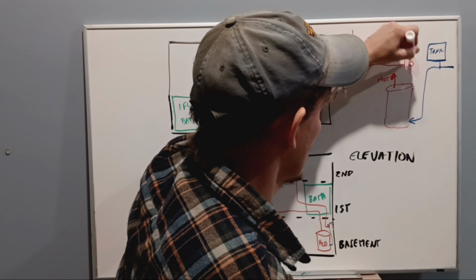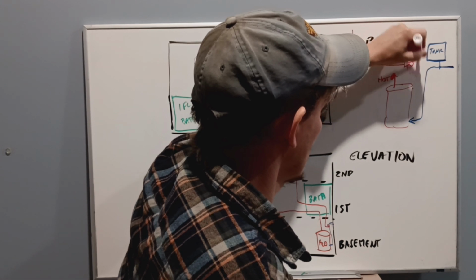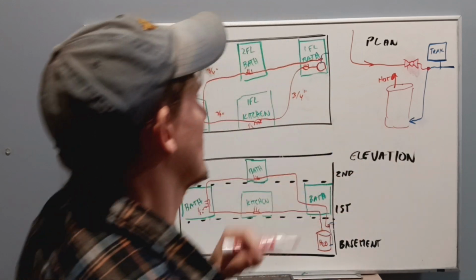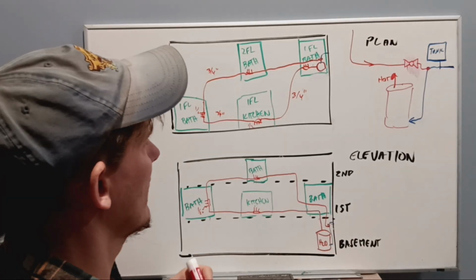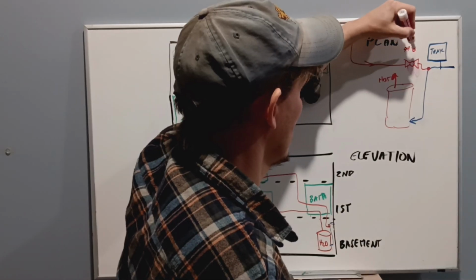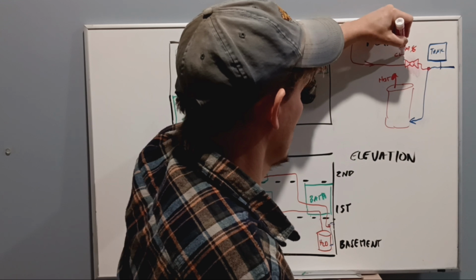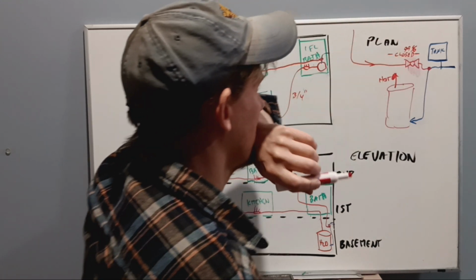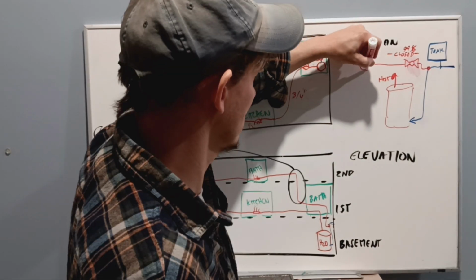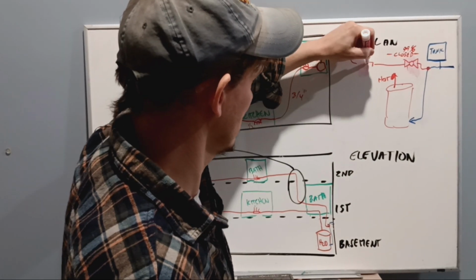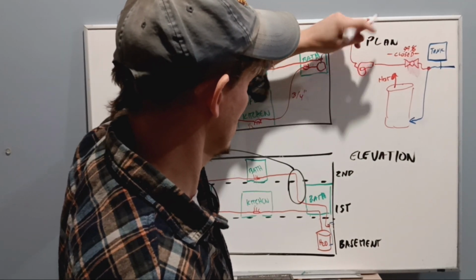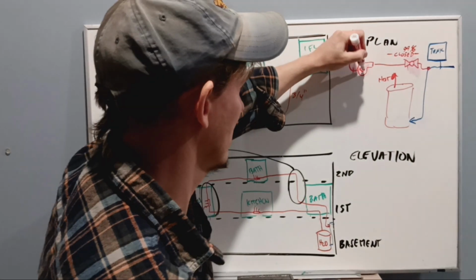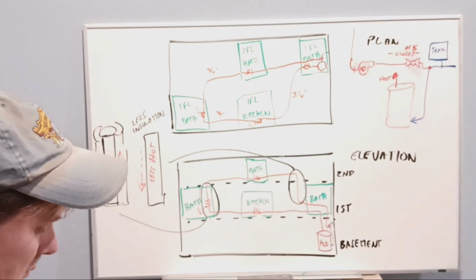In a passive system, there is no pump, and the return line goes through a throttling valve. In my system, I use a globe valve that is open in just a crack. The purpose is to let cool hot water return to the tank while also preventing cold water from running backwards through your hot water system. Setting this perfectly requires some time and adjustment. This system saves the electricity of running a pump to cycle the water, which is arguably not needed since the passive system will gradually recycle the water as it cools.